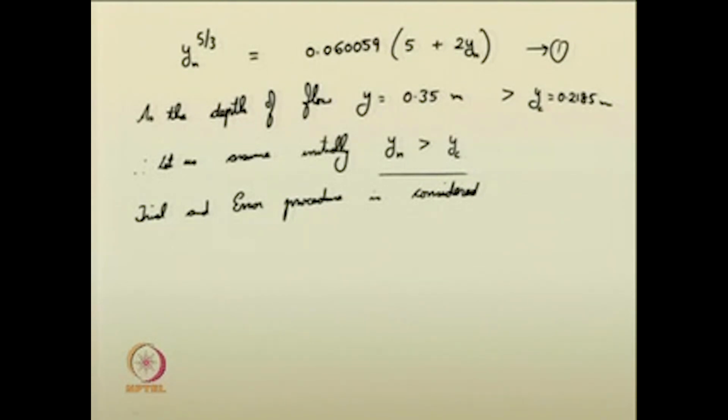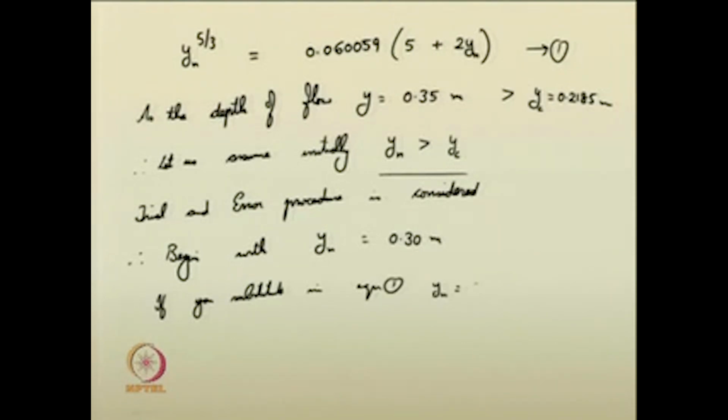So, to begin with, you can take any value of y n greater than y c. I am just beginning with y n equal to 0.30 meter, just to see. If you substitute y n equal to 0.3 in equation 1, see whether the equations are matching or not.